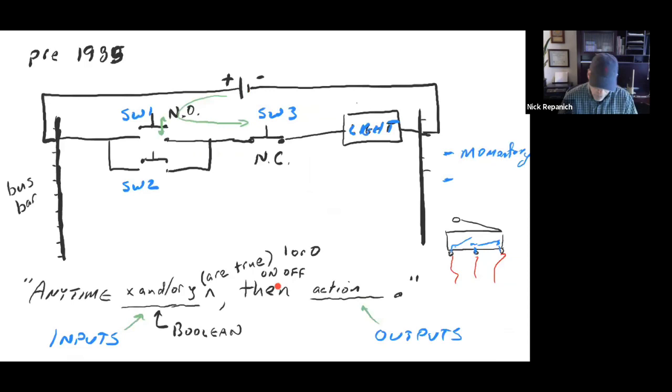So let's go back to our ladder logic. And we know that we can have multiple circuits. So let's make another light. Let's make a motor that turns on when the timer times out. We turn the motor on for a certain period of time, and then we turn the motor off, okay? So you always start over here on this side.